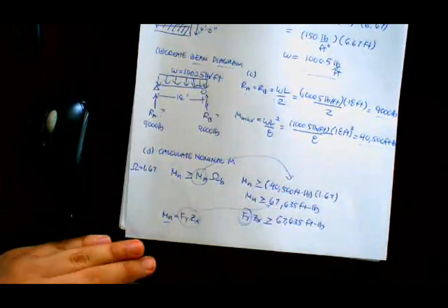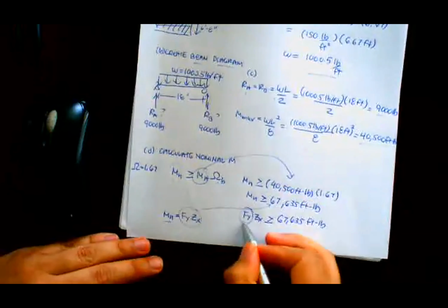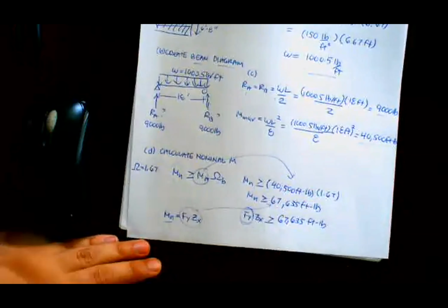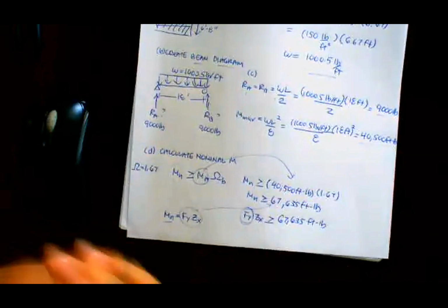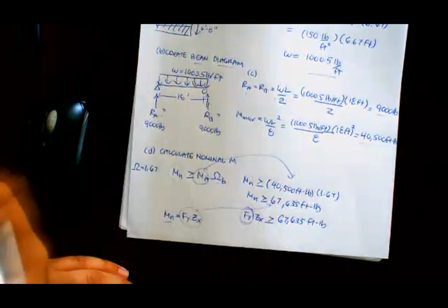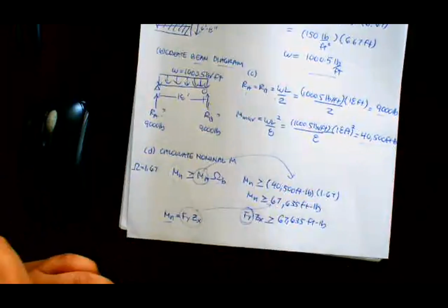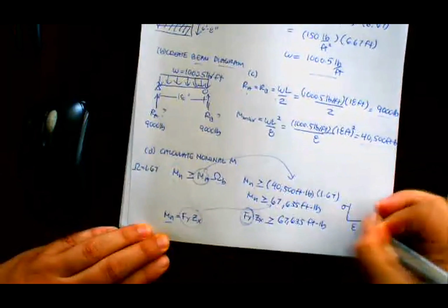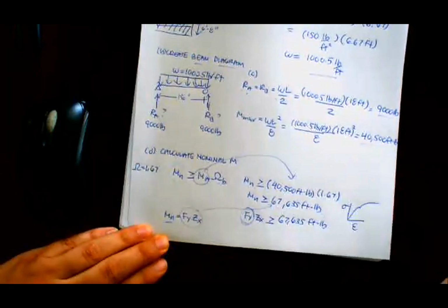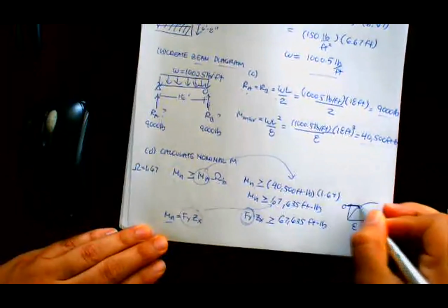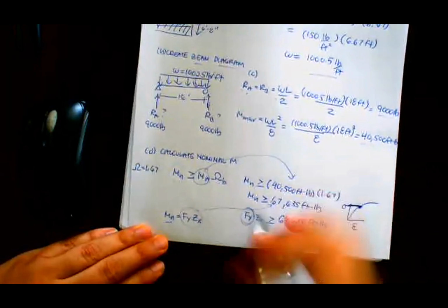And just to jump back into POE, Fy is the yield stress of steel, or of any product. Fy means the yield stress of the material you're using. If you remember back to stress, the yield point is the yield stress if you go onto the y-axis. So when I look at stress over strain, the graph looks something like that. The yield point is right here. So what Fy is basically saying is, what's the stress at the point of failure? And it was given to me.